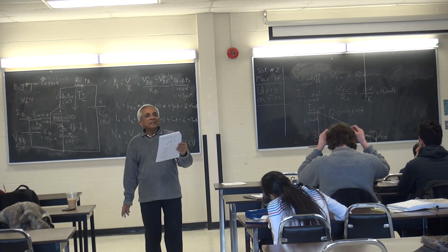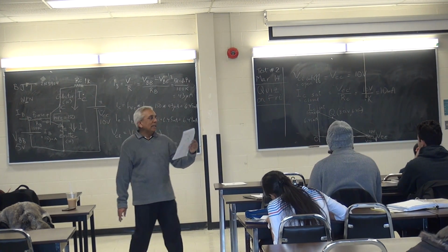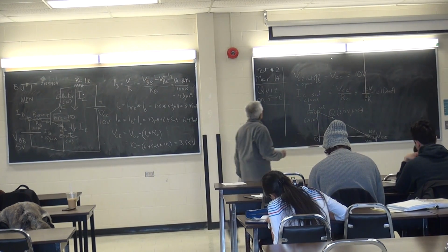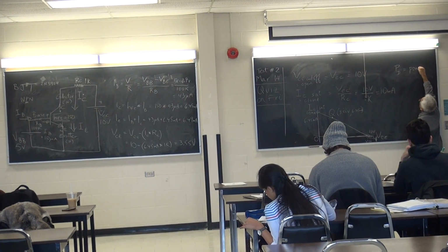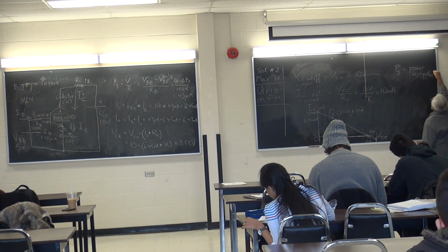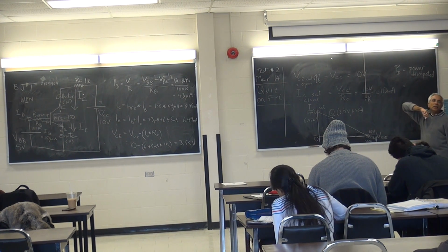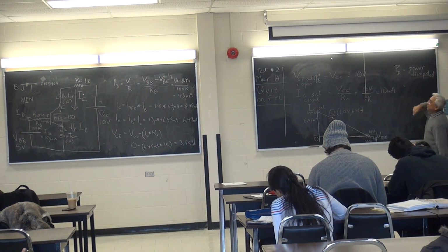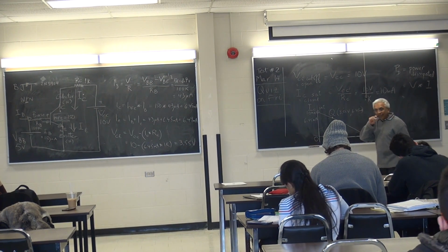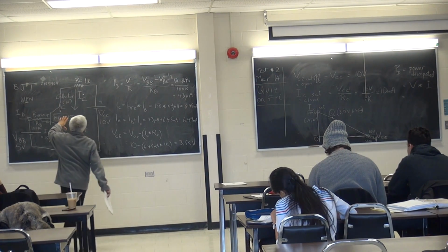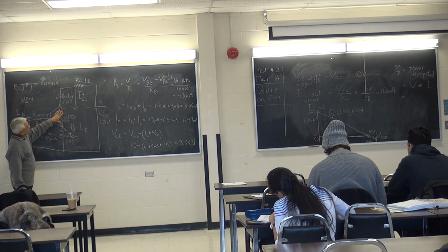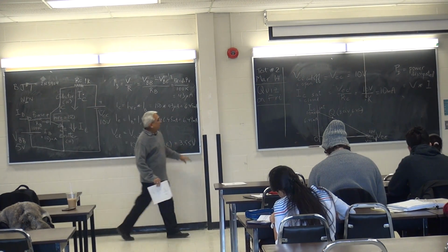Make sense? So there's one last calculation I have to do. PD. What's PD? Power. Power dissipated. Power, we know, what's the formula for power? V times I. In a transistor, what is the V value? The voltage from the collector to the emitter. How much? 3.55.